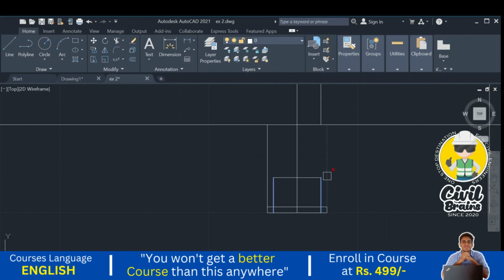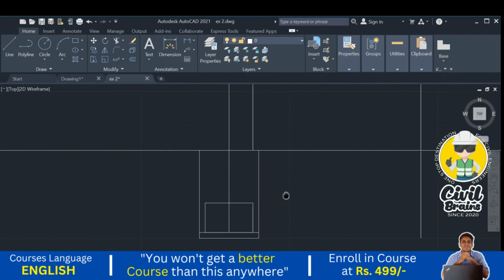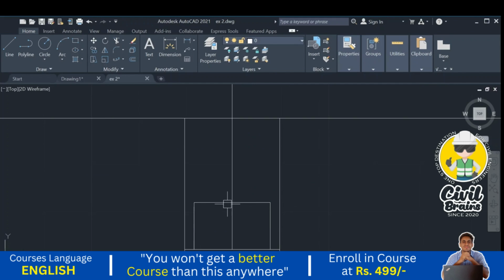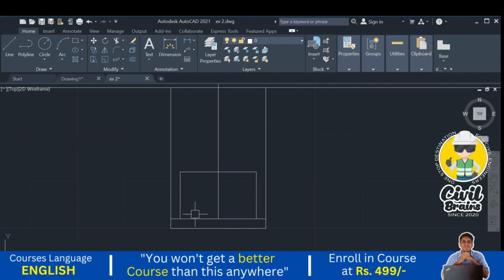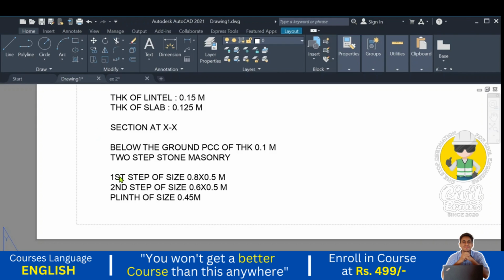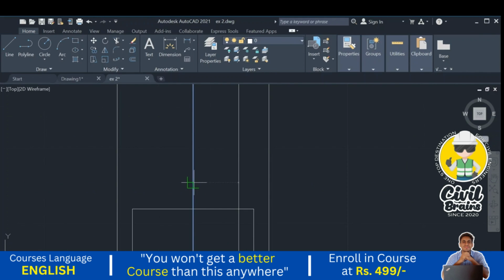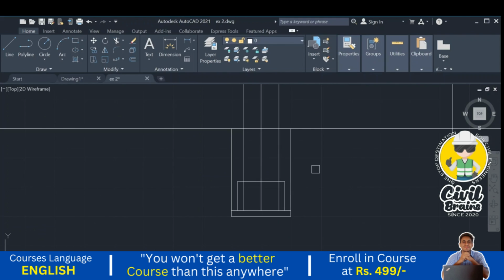So now just trim the extra parts. Whatever extra part is there, we just trim. The first step of the stone masonry we have drawn. Next, second step. What is the size of the second step? Second step's stone size is 0.6 by 0.5. So I just draw this one. Offset, press enter. 0.6 is the width, so 0.3, 0.3. Total is 0.6. And offset, what is the height? 0.5.